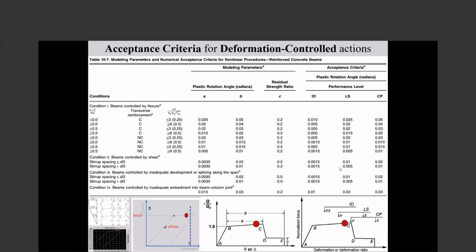Therefore, the general characteristics are quite different. For taller ones, the boundary elements are very important. Most of the ductility comes from the boundary element, but at the same time, they are very sensitive to the amount of compression in the compression part of the shear wall.